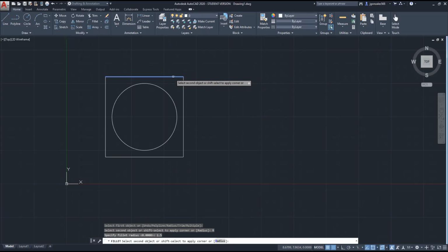See, now it's going to fillet the corner here. See that? Now, so I don't have to keep doing that over and over again, let's do one more time for practice first. So fillet, select the object, choose how much I'm going to fillet by choosing a radius of 1.5, and then click that other side here to connect it to.